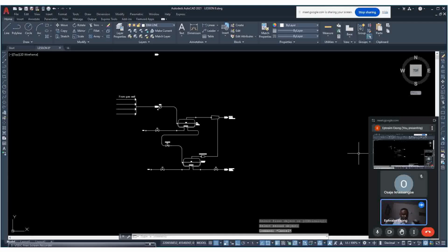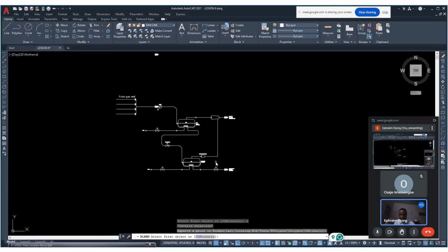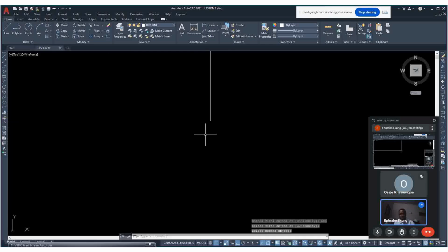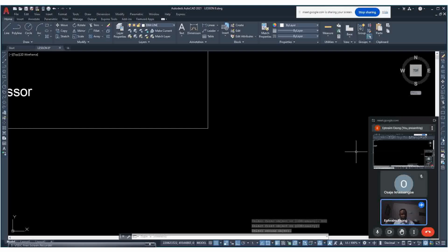Not working. Go to fillets. Type R, enter. 600, enter. Click at this edge, click at this edge. If it's too big, it's as if it's too big. Okay, so let's reduce the radius.